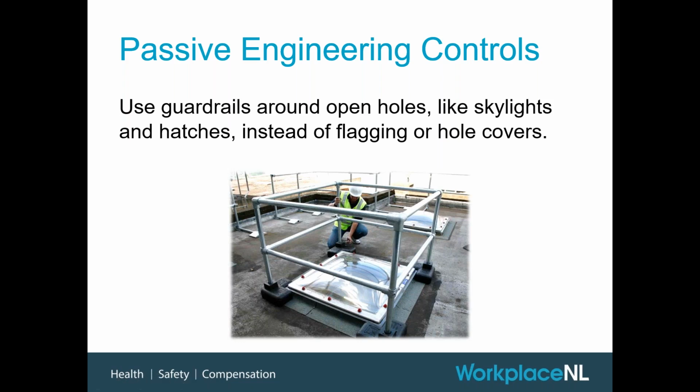If you do have an open hole, and skylights is one that we've had, unfortunately, a few fatalities around in the past. Again, a guardrail is really the ideal way to deal with that hazard.